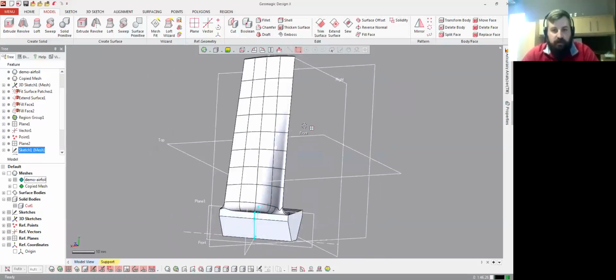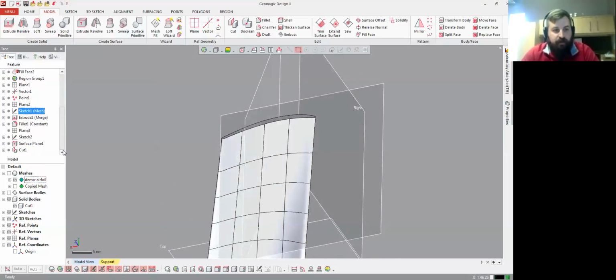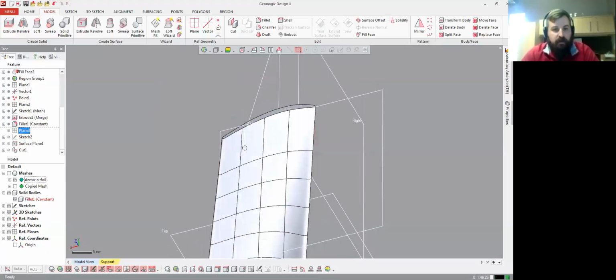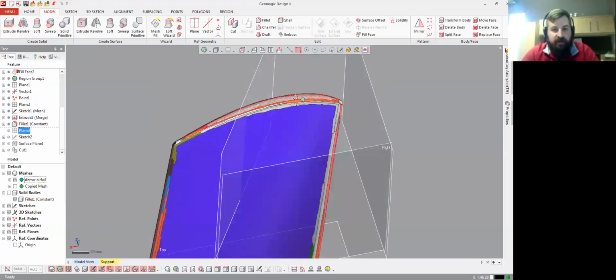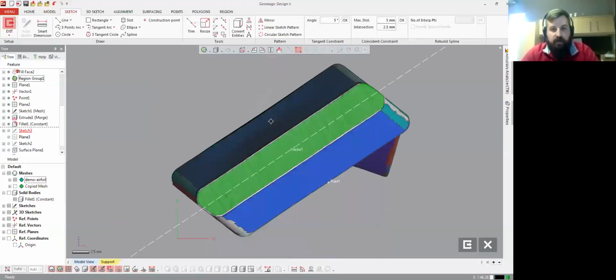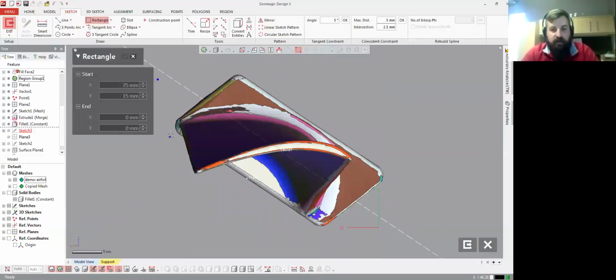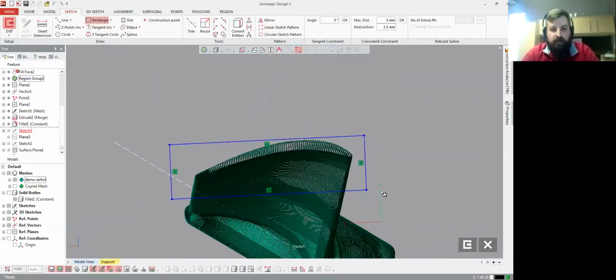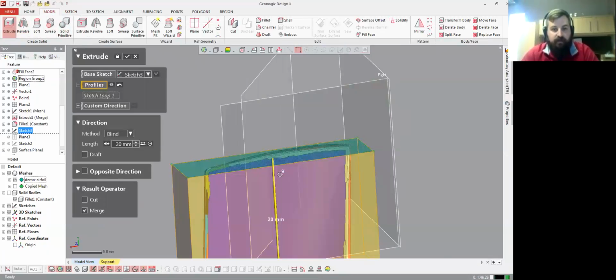of a blade. So an alternative to trimming this, if we want to use sketches, if I roll back my tree and I go to my mesh, I can utilize this as a sketch as well. So if I want to go to sketch and I want to sketch on this plane, and I can just create a simple cut feature, and I can use that to cut with.